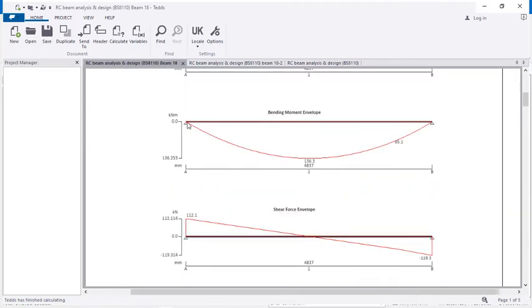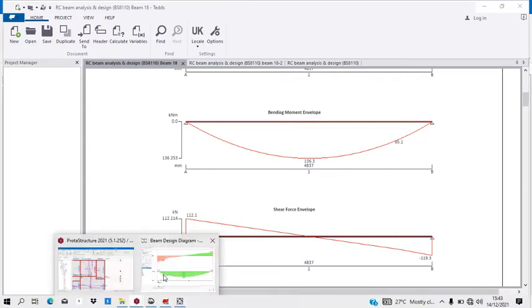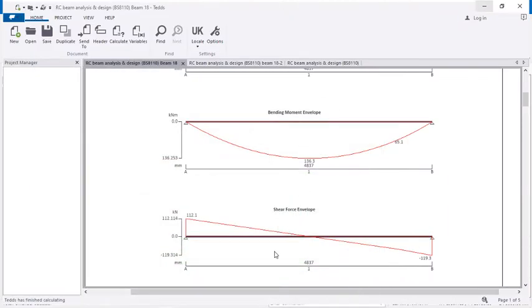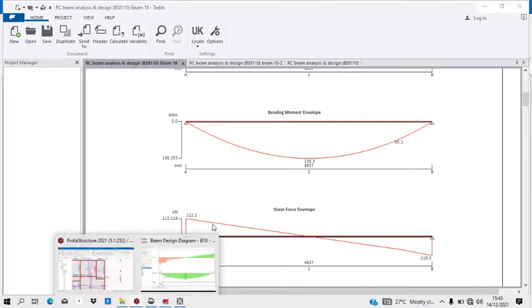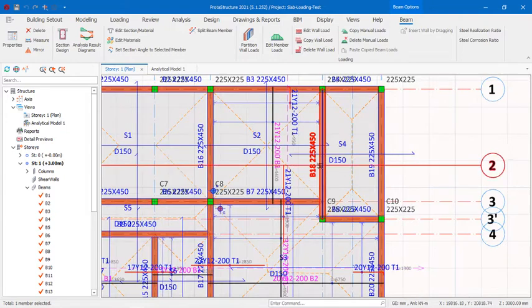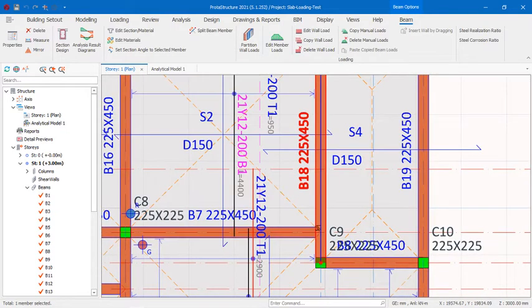Now, mind you, you understand that this is assumed as simply supported. And of course, in the software, there's always a case of fixity, and it will always calculate the fixed end moment at the end for that particular beam. So you can see that in this case, the effect of beam 7 is not showing, which is acting as a point load. Let me close this.